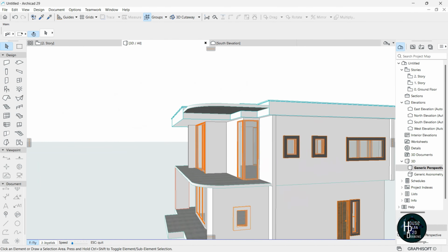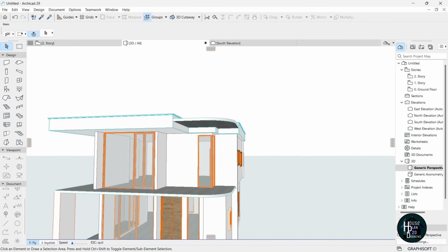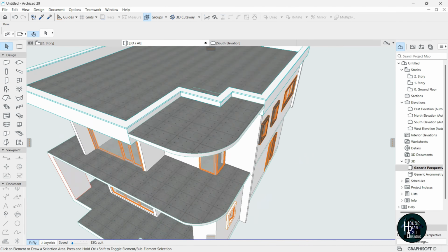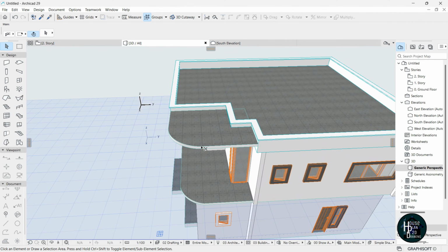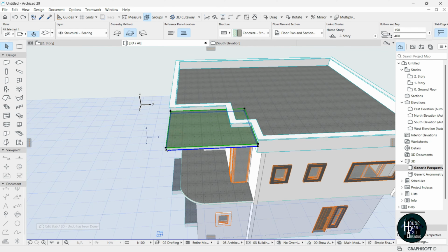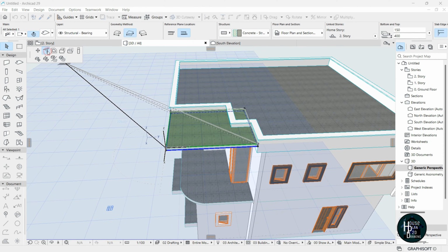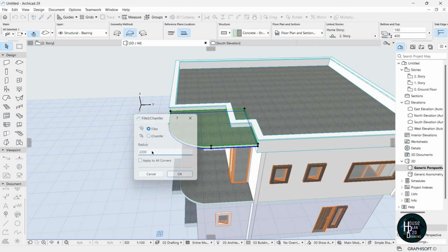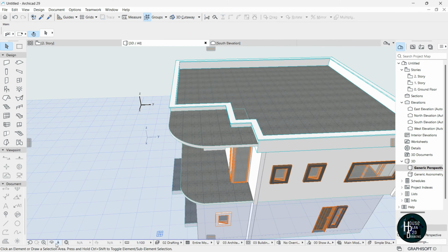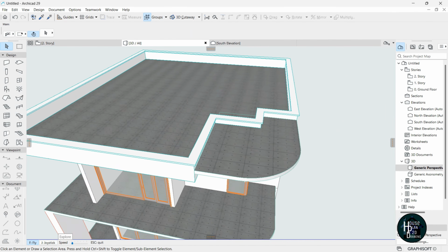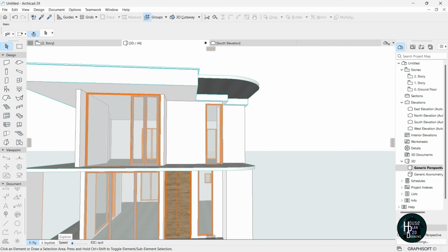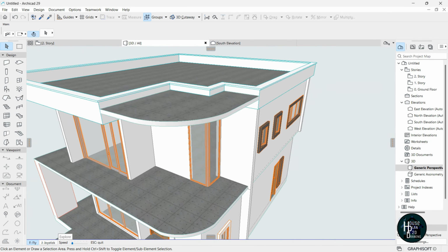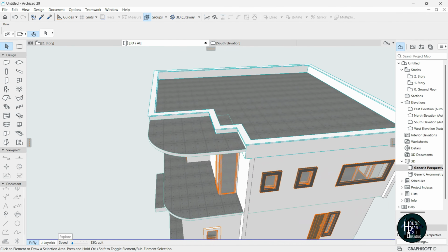If you don't like the way it actually arches, you can decide to increase the arch. It all depends on your choice. Okay, I can decide to just press Ctrl Z. Click this, click on this node again, click on the fillet and chamfer, click on the fillet itself, and let's give it a distance of maybe 2.2. Click enter. So that's also going to arch again for us. Okay, so you can decide to just work on it and see what works with whatever you feel is the right thing to do.